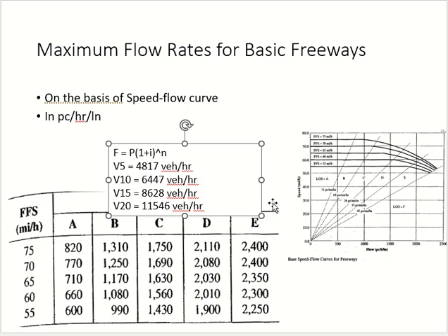These are two, right? What's the third difference here? These values in the table are per lane. The values which I have are not per lane, so I cannot compare them obviously. The values which I have are vehicles. These values in the table, or in the graph, are passenger cars. Even if you draw your own curve, it will be passenger cars. Keep it in mind, this is default. The equation which you are using is in passenger cars. So all these values are in passenger cars, and I cannot compare passenger cars with vehicles.